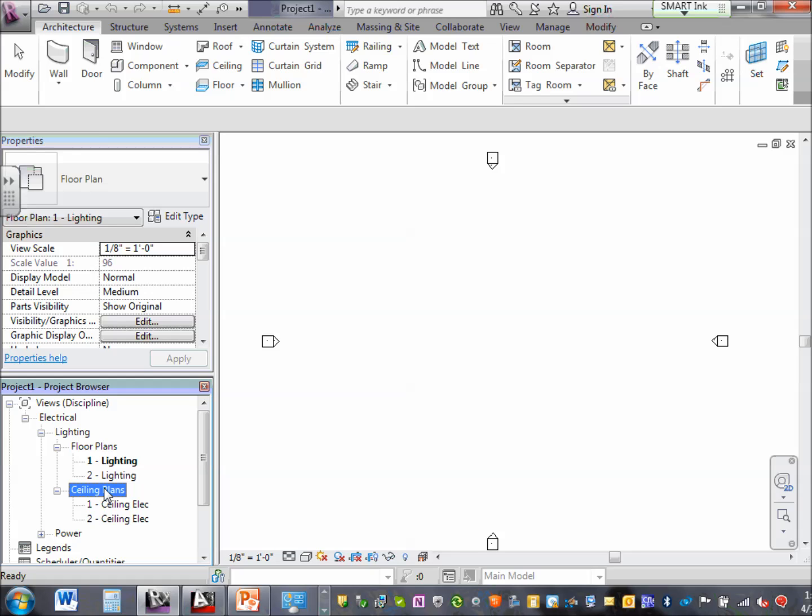You might not be able to see it when you're looking at it from one view, but be aware that probably the major and most important thing when you move from CAD to Revit is to pay attention that everything that you drop has an elevation. So when you send it back to the architects, your receptacle might be sticking up in the air with nothing in it.